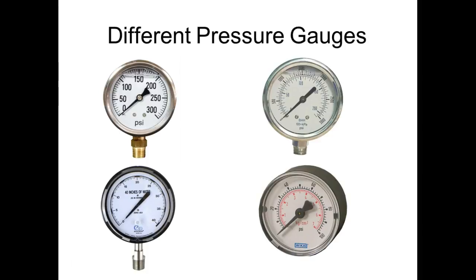Yeah, most air compressors are like that. Now we do have some continuous flow compressors, but they're pretty expensive, and they give us a constant flow at a pressure. But most of our compressors operate on a storage tank. We compress air and store it in a tank, and then we use it out of the tank.